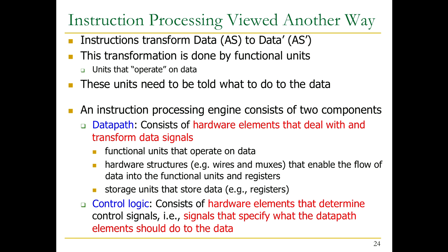On the other hand, control logic basically consists of hardware elements that determine the control signals. Basically, it's signals that specify what the data path elements should do to the data, right? Which mux input should be taken, right? Which one do you select? Or what should the ALU do to the data? Or which register should you read from, right? Which register IDs should you use when you're reading from the register file?